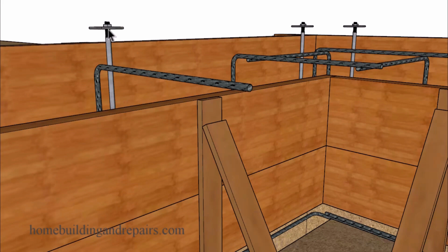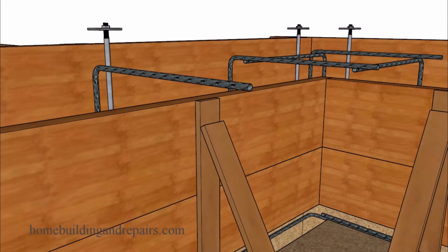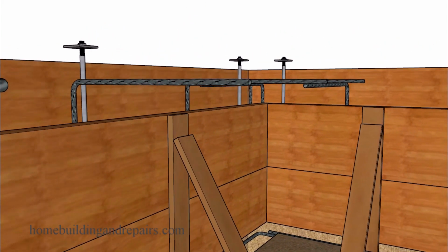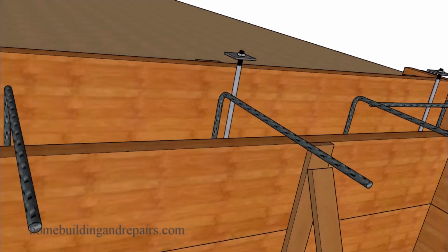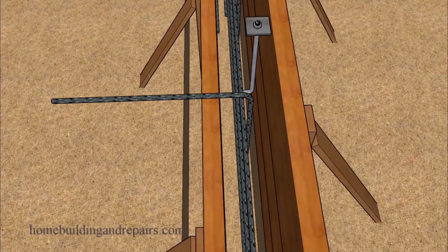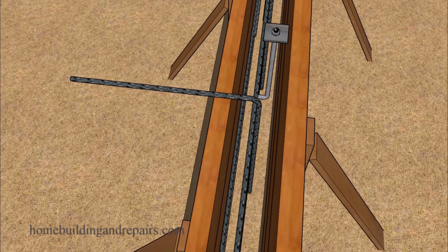This information right here would be worth watching the entire video, because if your anchor bolts are longer than the thickness of the slab, then they're actually going to be embedded in the stem walls. And yes, I have seen that mistake made, even though I have not had the pleasure of making that one myself. And even though I have the rebars spaced 20 inches on center here, you might need to space them a little closer or even a little further apart.